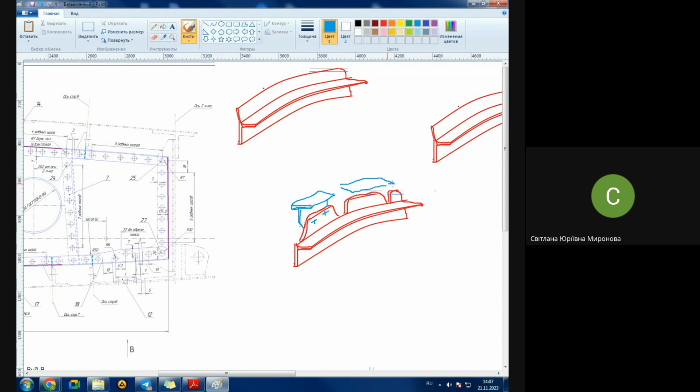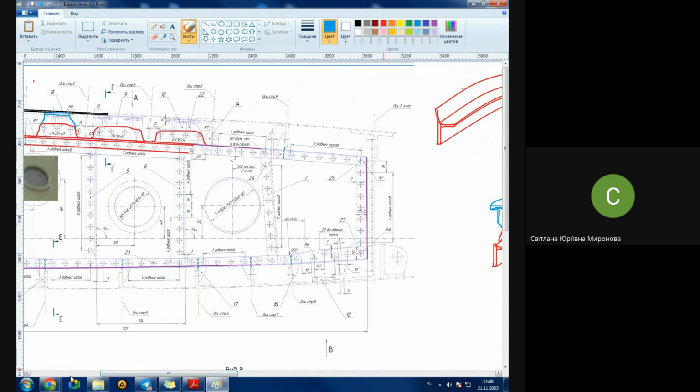We call them compensators. They are necessary to compensate. They are included on purpose, let's say, by the designer. They serve a very important function. They compensate errors of assembly. We might use cheaper, less accurate methods of assembling the rib, but during assembling, they are, on one hand, necessary to join the rib to the skin.